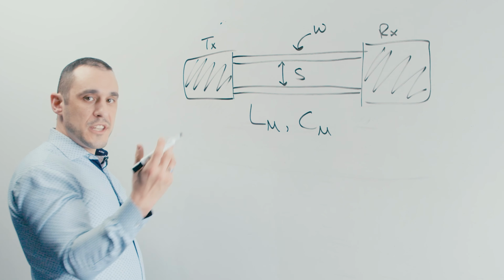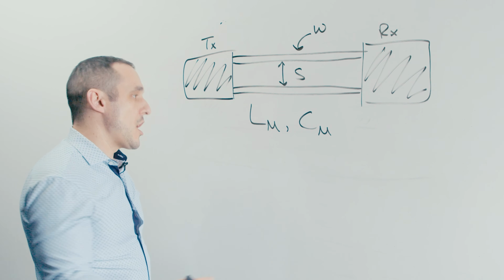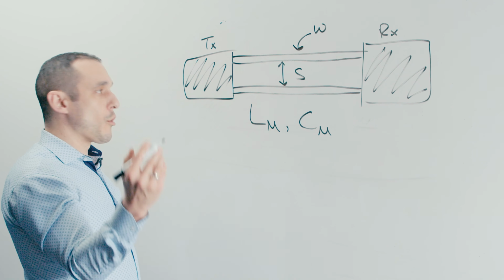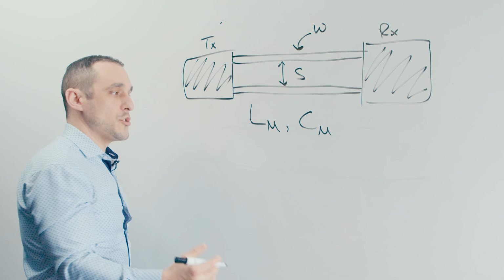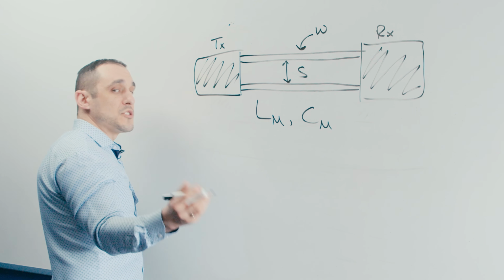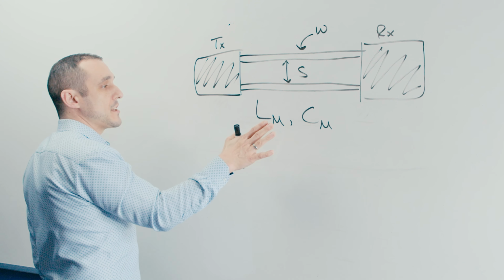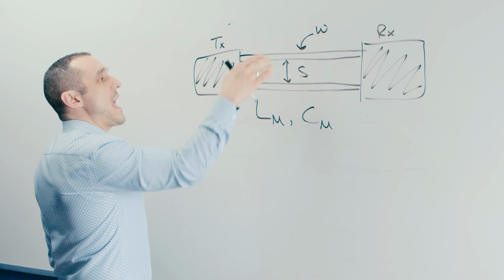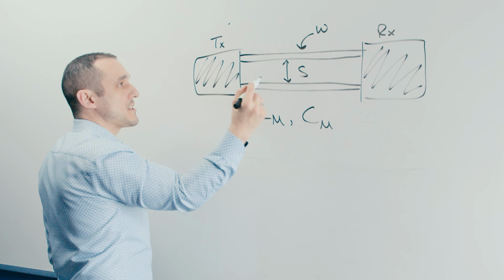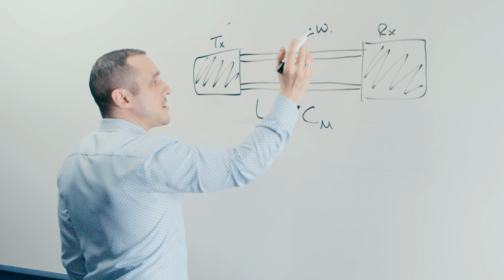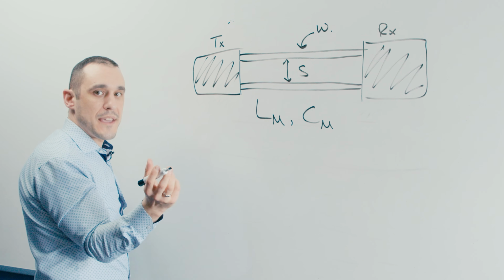But typically when we bring these up, we're bringing them up because we want to talk about differential impedance, or we're talking about crosstalk between two traces. So now, what happens to crosstalk if we were to then take that ground plane and move it closer to these two traces without changing the width and without changing the spacing?